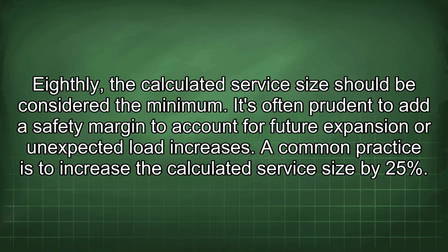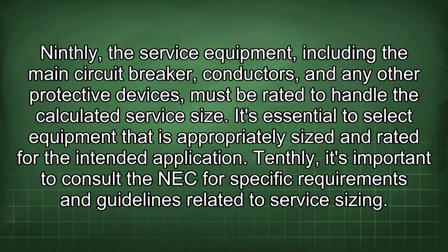Eighthly, a calculated service size should be considered the minimum. It's often prudent to add a safety margin to account for future expansion or unexpected load increases. A common practice is to increase the calculated service size by 25%. Ninthly, the service equipment, including the main circuit breaker, conductors, and any other protective devices, must be rated to handle the calculated service size. It's essential to select equipment that is appropriately sized and rated for the intended application.